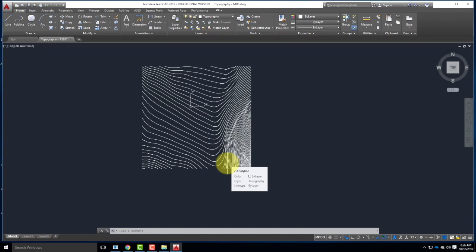So every contour goes up one foot. So it's not a huge slope. It's reasonably flat. You can build your building in a reasonable location and not have too much steepness to it. So it's relatively solvable. You don't have to, for example, have a split level because this hill's so steep. The hill goes up as you go down, if that makes sense. So this side is higher than that side. This is lower. This is higher.